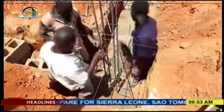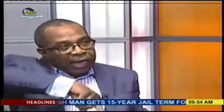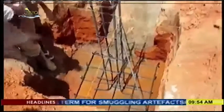It's a very elementary description. If you think of a reinforcing steel bar, if it's very skinny, it's a very tiny bar. If you load it, right, what do you think will happen to it? It will buckle. So those ties that we put on it, those things that hold it together, are meant to keep the length of it short enough such that it can carry that load.